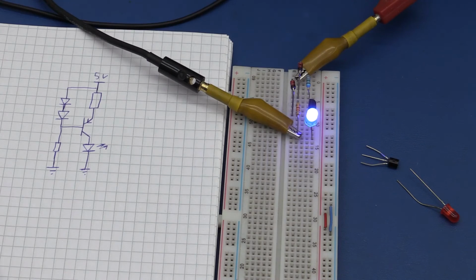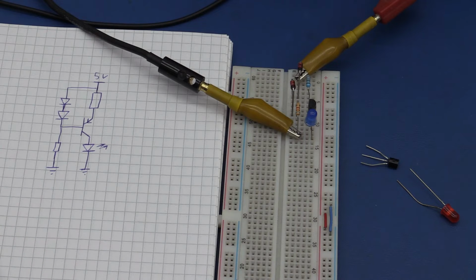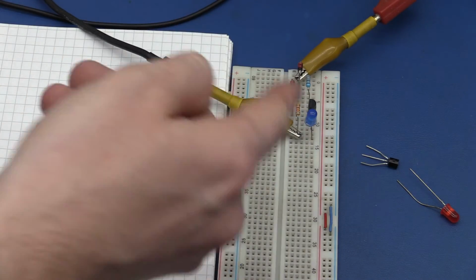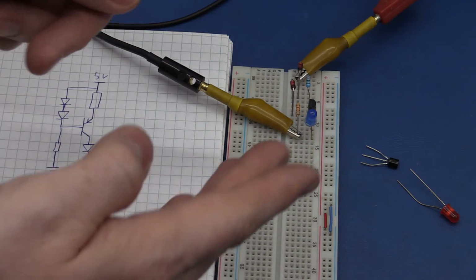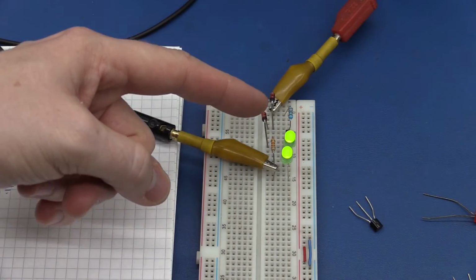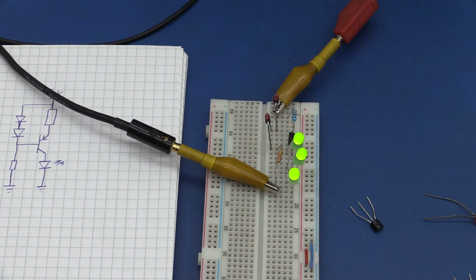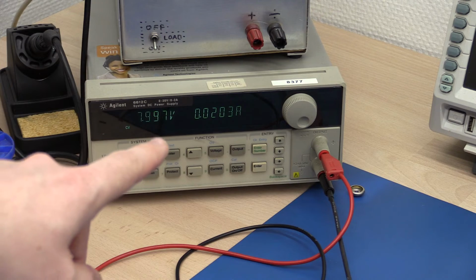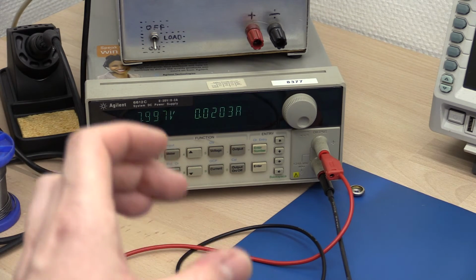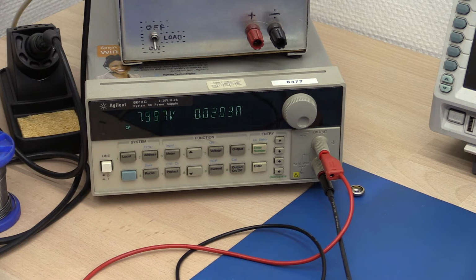And also a blue LED. Just note that the blue LED has a greater forward voltage, so now we are operating at 5 volts, but if we were operating at, say, 4 volts, maybe it cannot give enough current to the blue LED, because we do still need the minimum voltage. It's also possible to put more LEDs in series, and we will still keep the same current. So as long as you have the forward voltage of the LEDs plus the margin for the regulator or the dropout, then it will work.